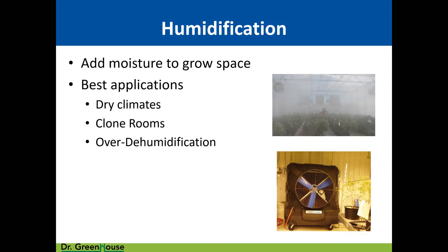or we over dehumidify the space when we first transplant young plants from another room that had a less intense environment and they're just not pumping the water yet. And now we're creating a very dry condition. This picture in the bottom right, by the way, is what one of my clients did to overcome that over dehumidification. They actually put in a big evaporative cooler in their grow room. Not ideal.